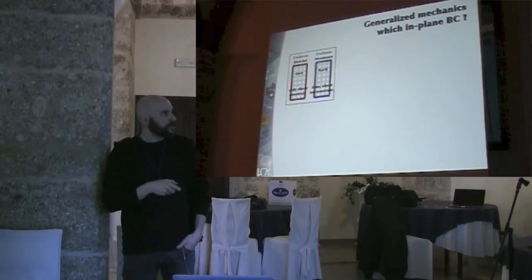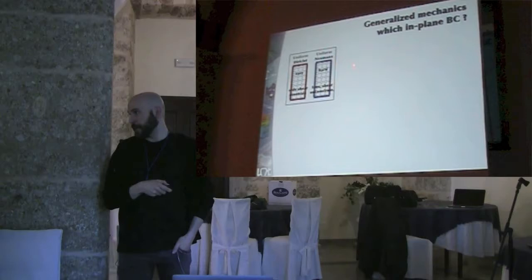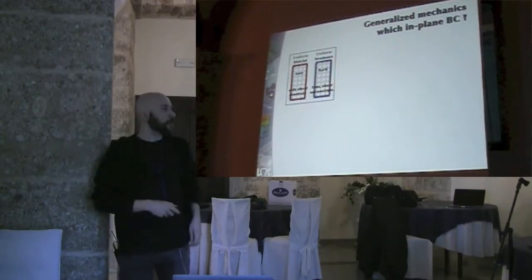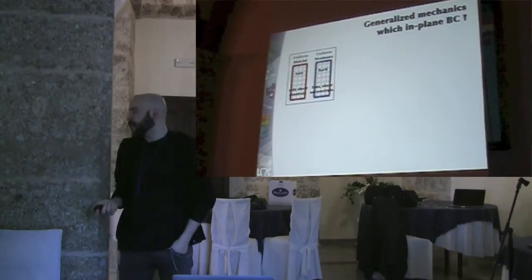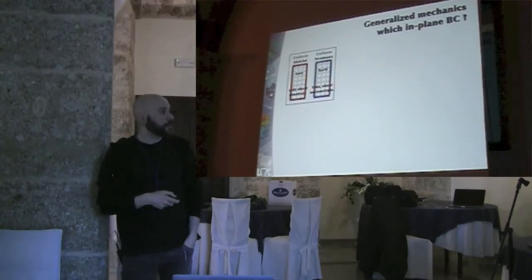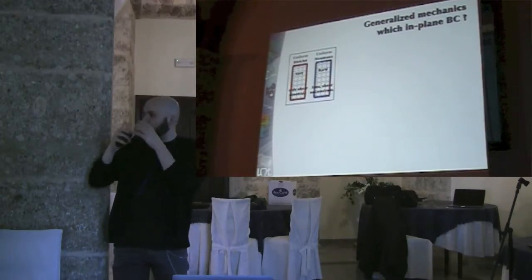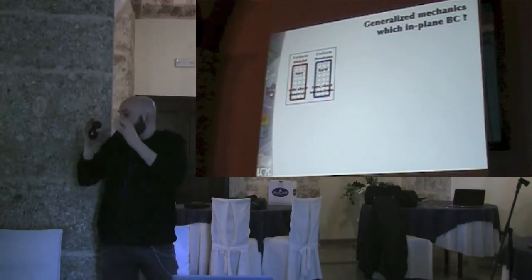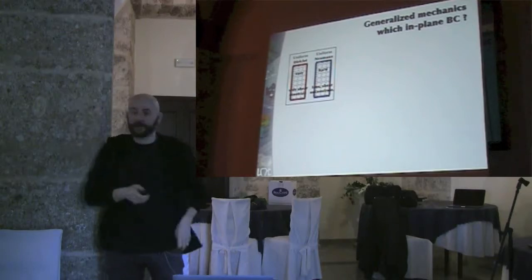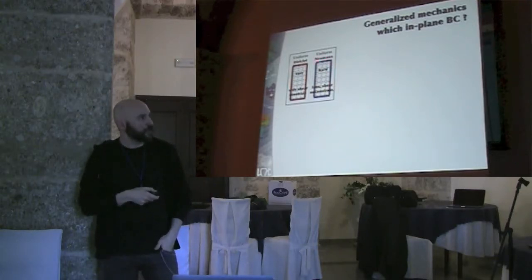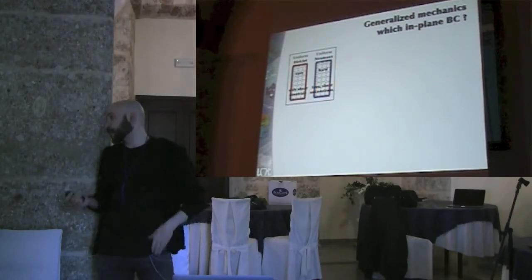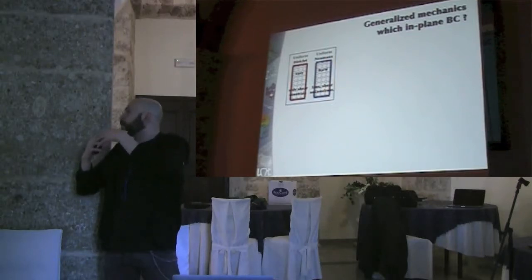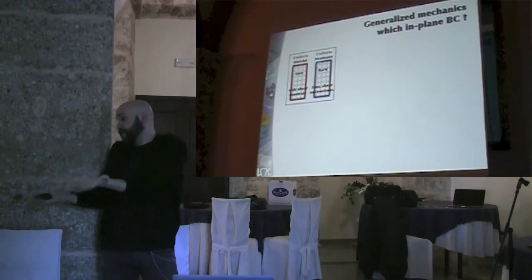Well, in this case, this one is very easy to do. I mean, you're just clamping everywhere. But in fact, you can only apply shear this way. And it's very constrained. I mean, if there is a specific kinematic that wants to develop, it is stuck by the clamping around the specimen. On the contrary, if you are using uniform Neumann boundary condition, you can perform tension, shear, and it's unconstrained. So you will see much more displacement. So it's interesting for full-field measurements.